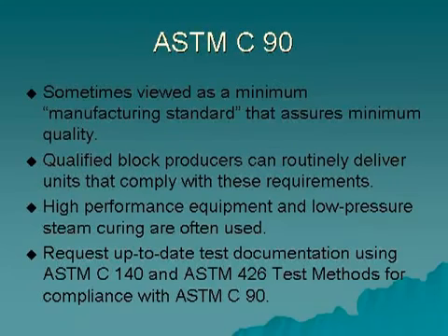ASTM C90 can be viewed as a manufacturing standard used by block producers to assure minimum compliance. Project submittals should always include test documentation from a qualified lab. Like other materials used in a project, a fundamental requirement for the administration and execution of assured quality programs are well-documented test results. Properly tested masonry products are important elements to assure that the masonry wall system will perform as designed.